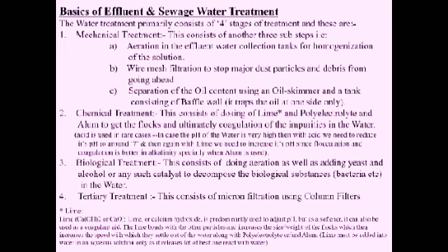Then with the acid we need to reduce the pH to around 7, and then again with lime we need to increase its pH, since it is evident from experiment that flocculation and coagulation is better in alkalinity, especially when alum is used for coagulation.